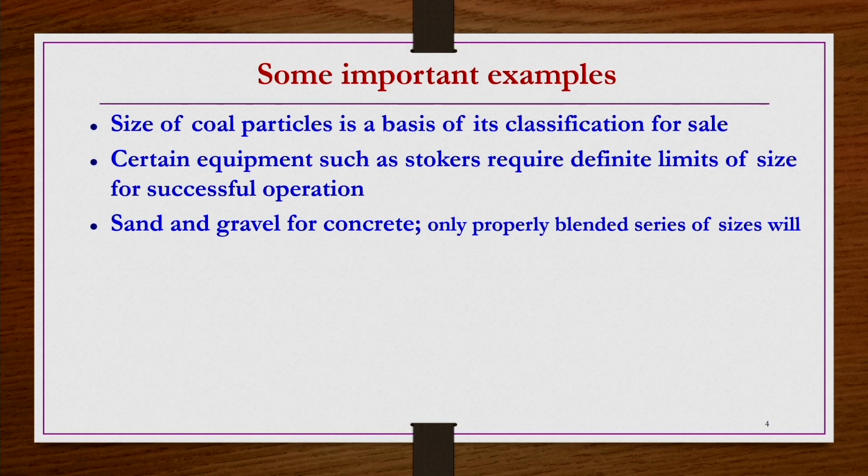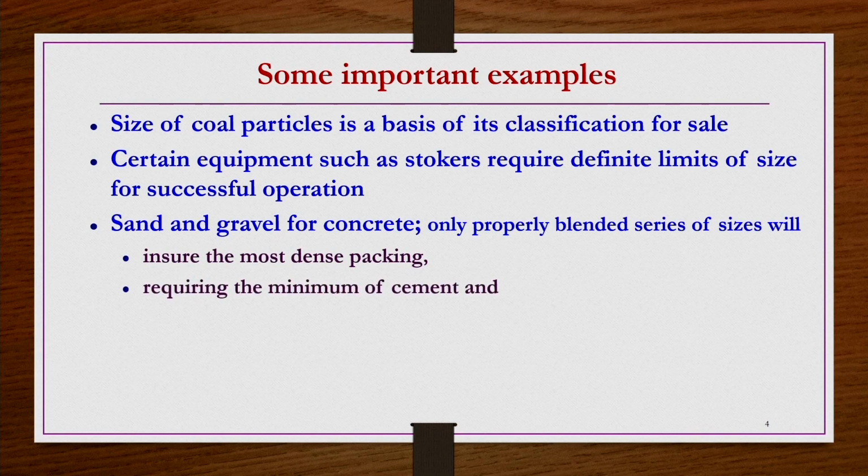So in this kind of construction purpose also, separation by size becomes an important component. When you have sand and gravel for concrete, only a properly blended series of sizes will provide the most dense packing, requiring a minimum amount of cement and securing the greatest strength without any voids. So here also screening is an important application.